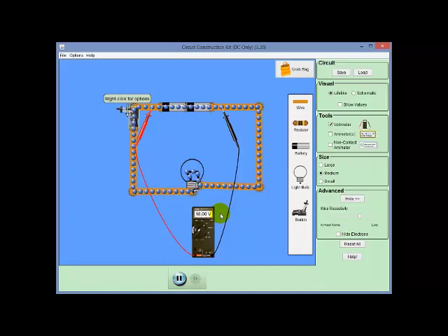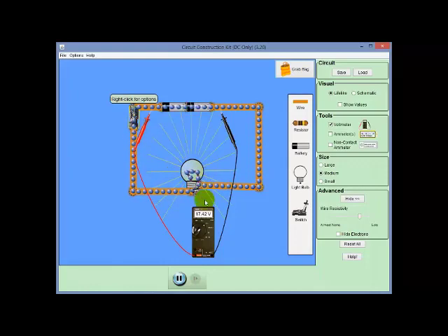It goes up to 18. So when the switch is open and no current is flowing, the voltmeter reading across the battery is 18 volts. Just to prove to you, look there, across the light bulb it is zero. There's no potential there, but over here it is 18. Okay, if I then close the switch, look what happens. Yes, it drops down to 17.42.